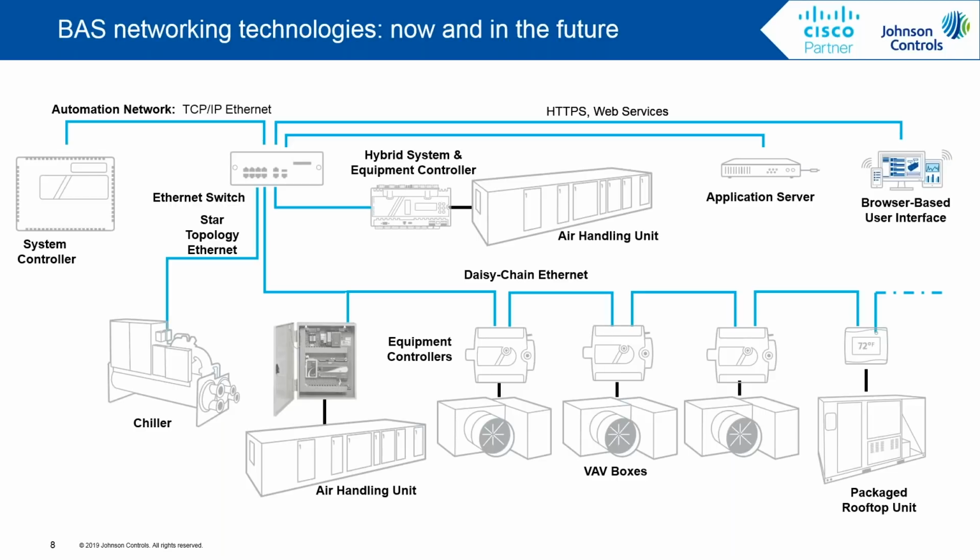Ethernet connections use crimped RJ45 plugs, which seem to provide more reliable node connections than screw terminals. Ethernet also has a much higher bandwidth, eliminating slow or busy networks, and IP Ethernet can handle multiple networking protocols. So your physical networking infrastructure can be shared to converge with or to integrate with other systems.